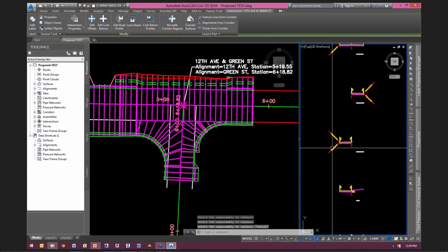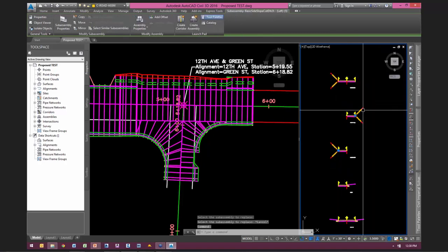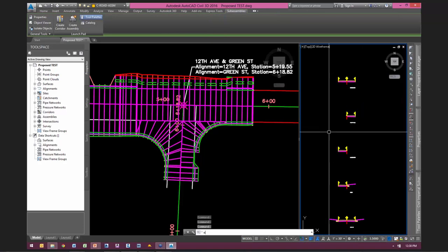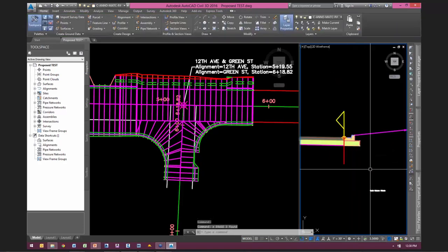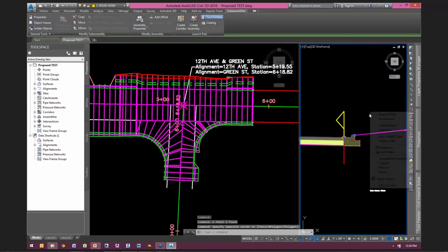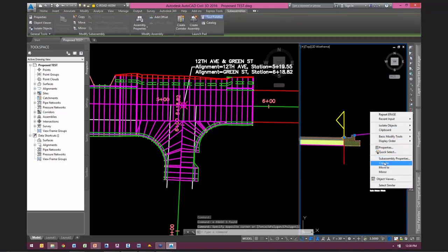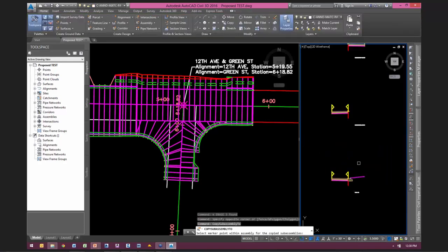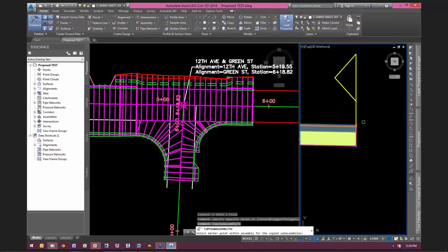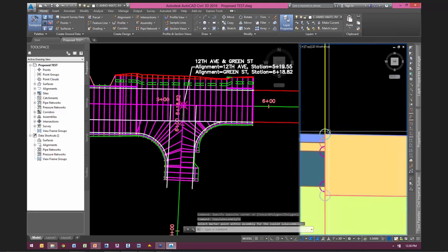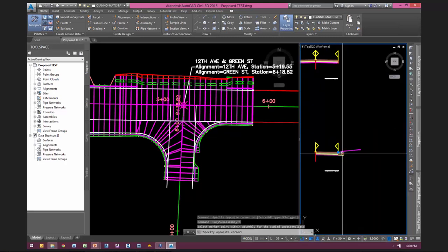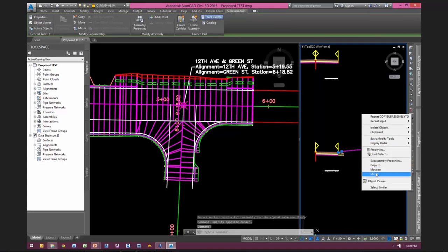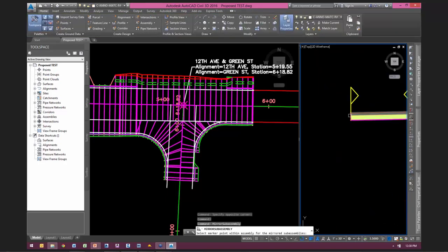And as I said, a few of these we need to delete out of here and then do a copy to command. Those of you familiar with subassemblies are familiar with this command, which is to grab any number of subassemblies and run the copy to command to take subassemblies as they're defined there and copy them up to any other assembly. So that's what we're doing here. When you do this, unfortunately, it won't hold the targets, but that's okay in this case.